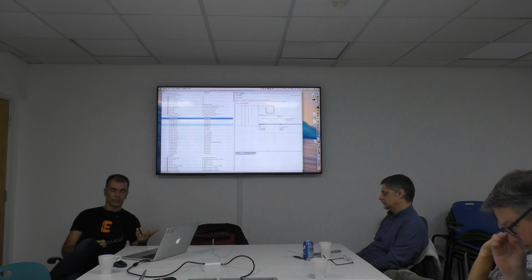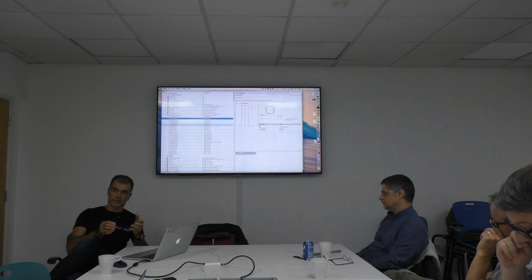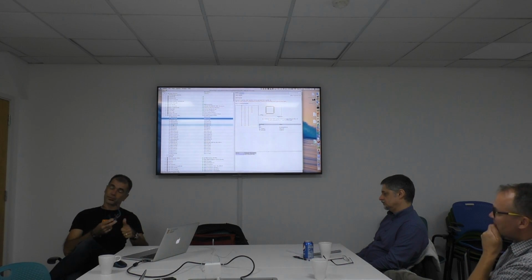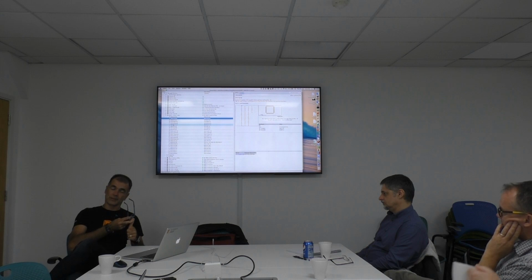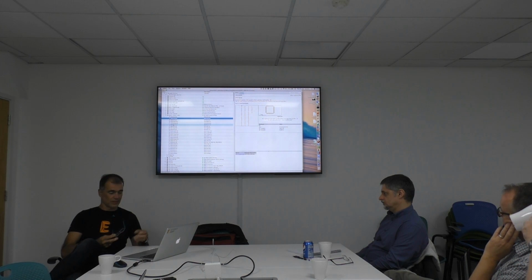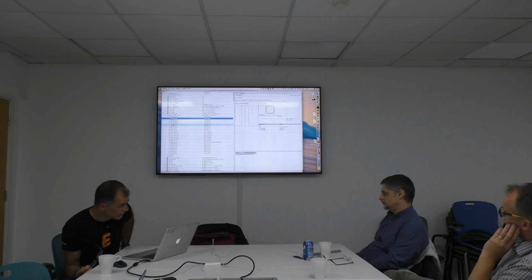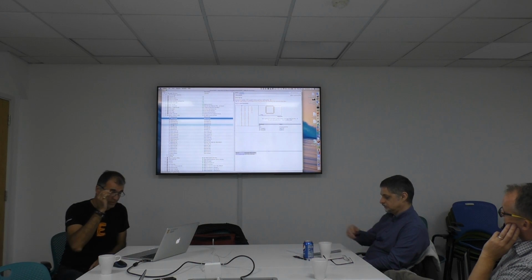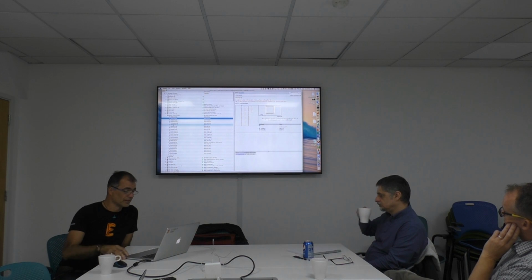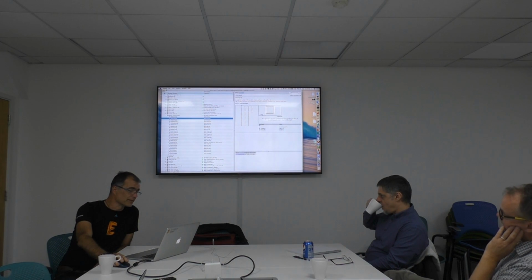And if you define a footprint, that's what we see in the board. Think of the sizes. This must be precise, because the package must fit onto your footprint on the board. If this doesn't fit, then it won't work. So that's very, very critical for the whole electronic design.